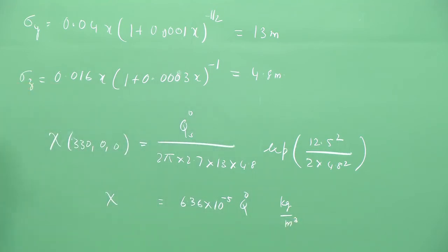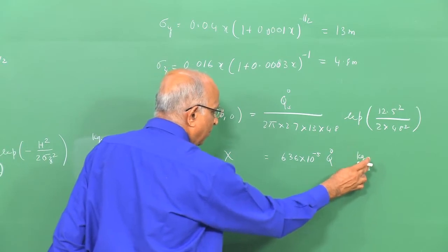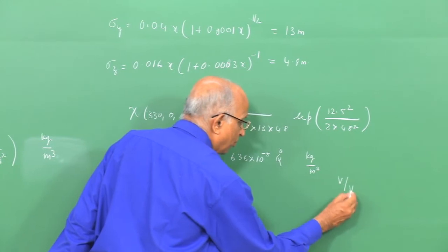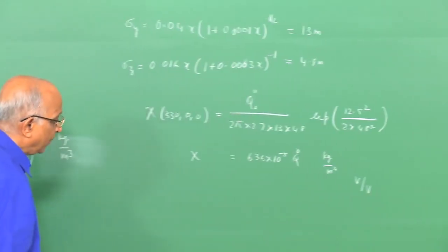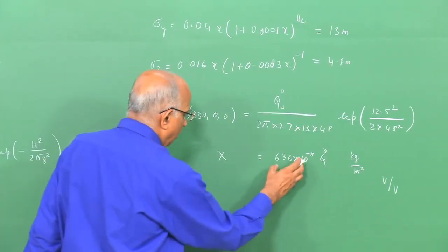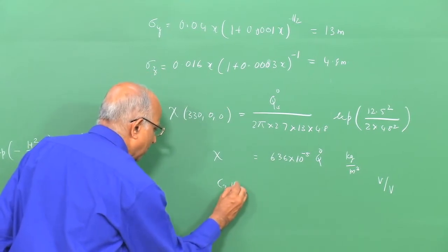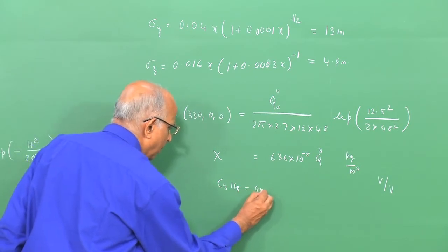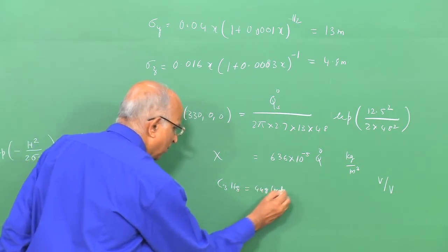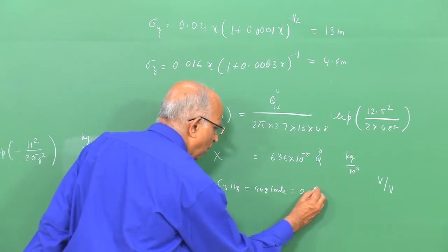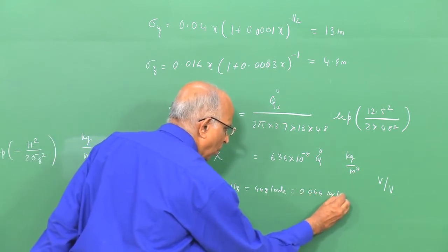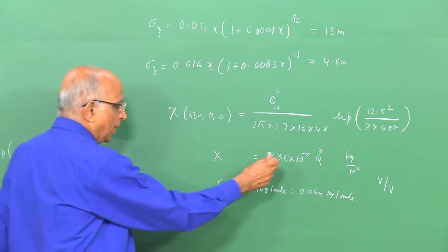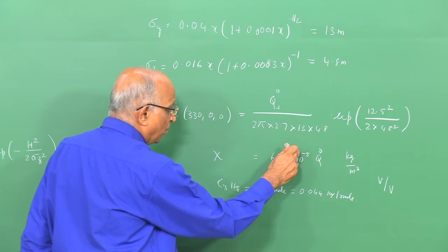Now, I would like to convert the concentration kilogram per meter cube into volume of fuel or volume of propane divided by the volume of the mixture, and immediately I note, well, propane has a formula C3H8, therefore 12 3s are 36 plus 8, 44 gram per mole is the molecular mass, or rather this is equal to 0.044 kilogram per mole, and we know a mole of any substance has a volume at standard condition of 22.4 liters.